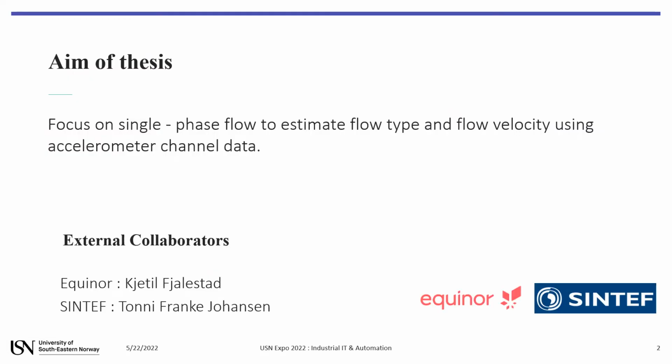The main aim of this thesis is to use the accelerometer sensor data, that is the vibration data, to determine what kind of material is flowing inside the pipe, whether it is water, oil, or gas, and estimate its flow velocity using machine learning.